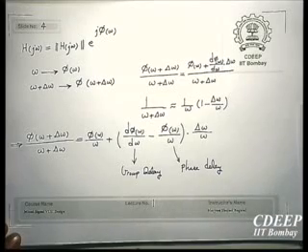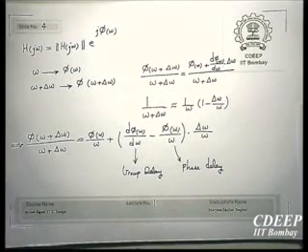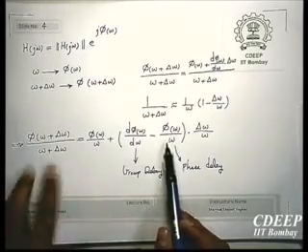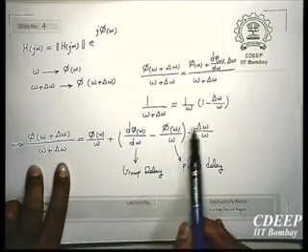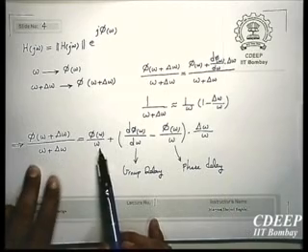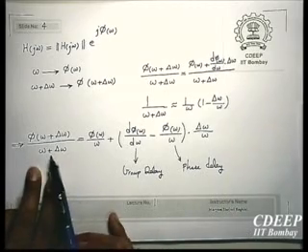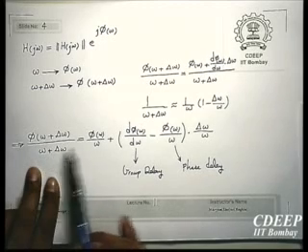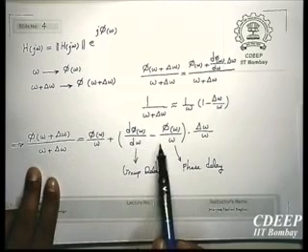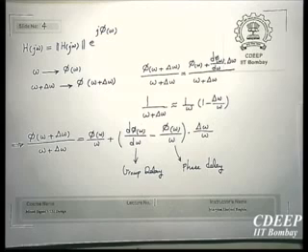So what we want: if the filter is completely linear phase, then these two are equal, which means the second term will be 0 and only the first term will remain. That is the reason that at any frequency the ratio of phase upon omega is a constant value. However, the difference between these two gives information on how far we are from linearity.